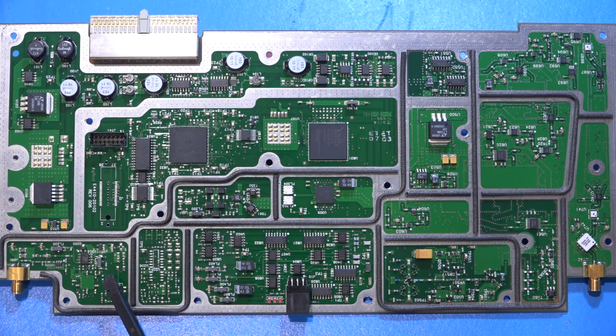Now the output of that programmable divider then goes into one of these two FPGAs. So they have two full FPGAs on this board. They are being used for fractional-N controllers, as well as all the glue logic required for everything else here. So that's just pretty complicated. Having an FPGA to do your fractional-N synthesizer is convenient, because it means you can program it and change its parameters, but at the same time it's quite an expensive way of doing it.